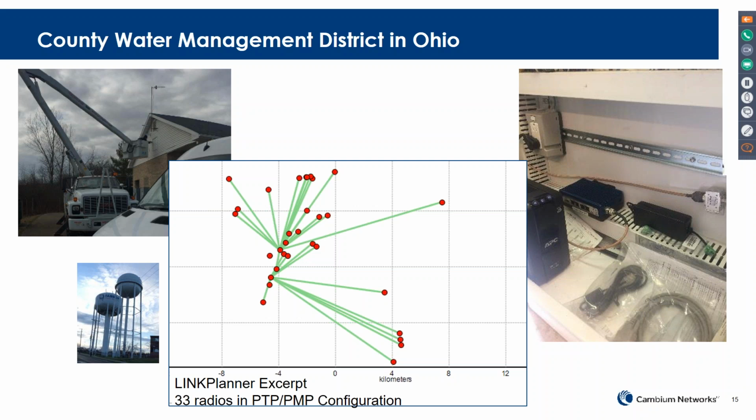This particular customer was using 900 megahertz unlicensed, and interestingly, they have a traditional interface for the RTU, a serial line based interface. So they're happy to have this cnReach, because we have a serial to IP converter, which allows the serial interface data to be converted to IP. So now they can achieve all IP based control.